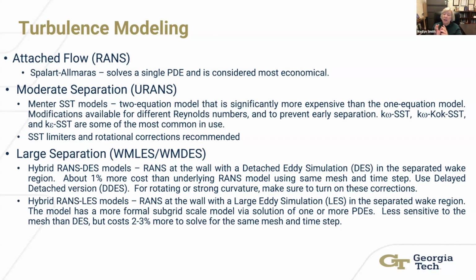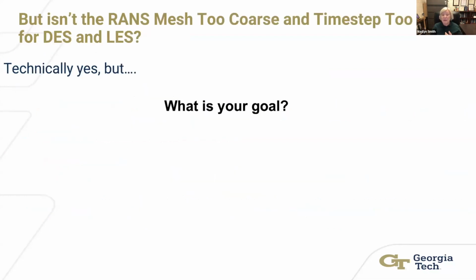Now, typically, you'll see, why don't you just use a wall model like we talked about instead of the RANS? Well, a lot of those reasons are because we're doing overset articulation, so we have to trim. And those things are very complicated, and it's easier just to use what we call CFD, CSD coupling.